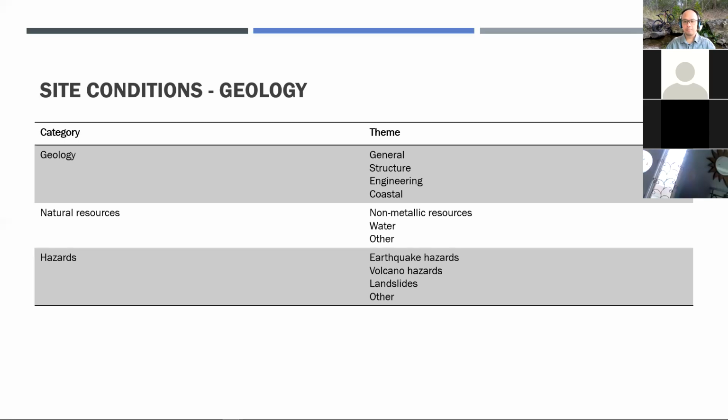Other areas may have a shallower bedrock depth. So if excavation for building foundations or for other site structures is planned or required for a site, then you need to take this shallow bedrock, deep bedrock into consideration. You may have to involve a certain level of blasting or other methods to remove the topsoil.